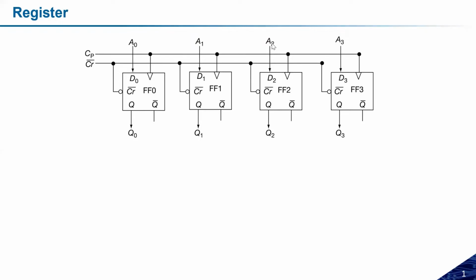And for counter designing, you need to toggle between 2 states, 0 and 1, or Q and Q bar, and for that purpose we can connect both J and K, and then I will get the T flip-flop. So this was the structure of all the flip-flops.